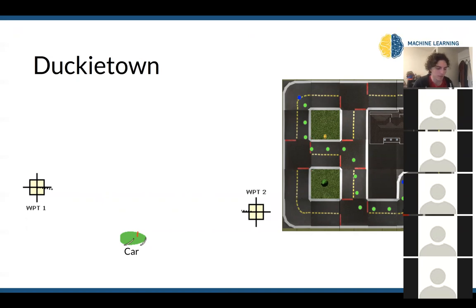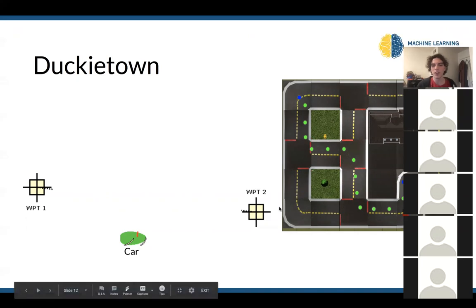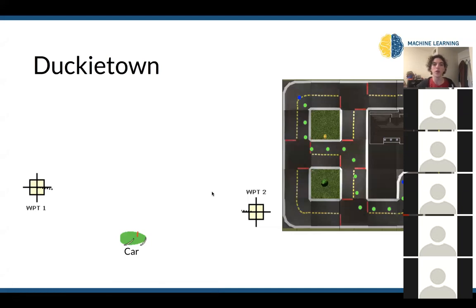Maybe x coordinates minus y coordinates of the car and the point that we want it to go to. That's a fantastic idea. So in general, what we end up doing when we have multiple dimensions of states and goals is we just do it along each dimension. For our case though, because the car operates on more of a forward driving and turning model rather than an X movement and a Y movement, we can't control this independently, but we can control forward movement and rotation somewhat independently. We're going to be formalizing this as more of how much to turn and how much to go forward. But that's the exact idea of how we can expand PID to more dimensions.